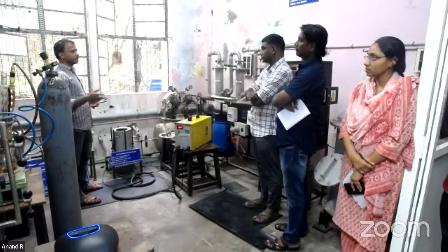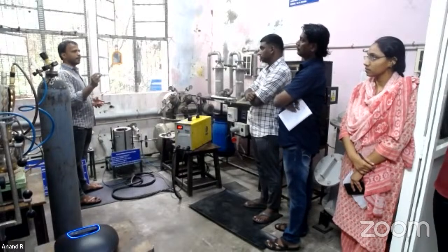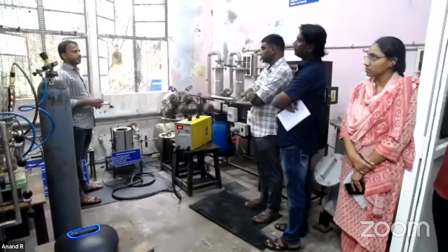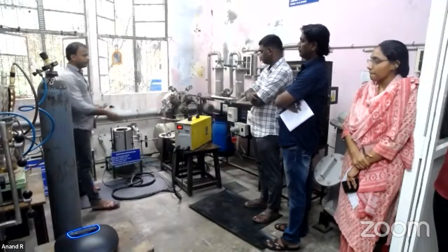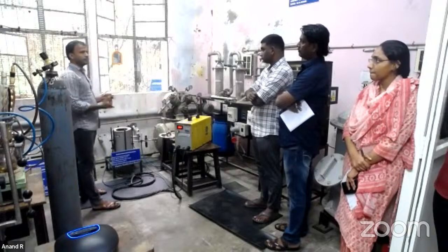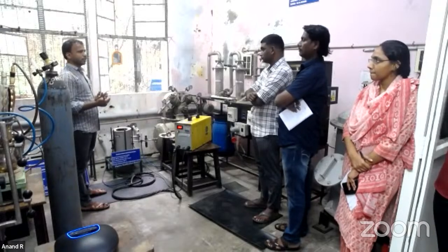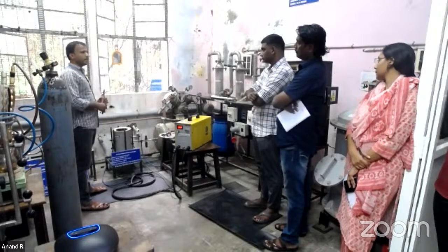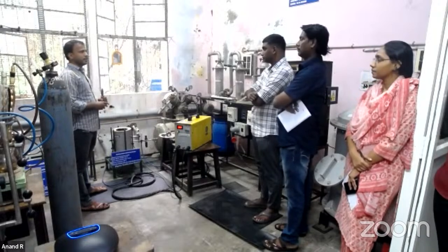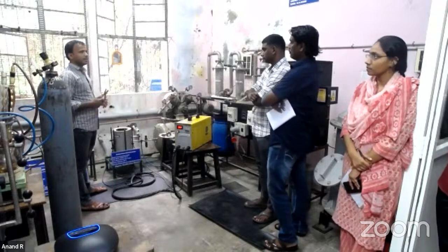If it is high voltage, high current, then the gap may be 5 to 6 mm for initiation. So the gap we can maintain depends on the current. If it is more than 100, then there is no need to make it close. The arc may be automatically initiated. For lab scale, 100 means it affects the electrode.